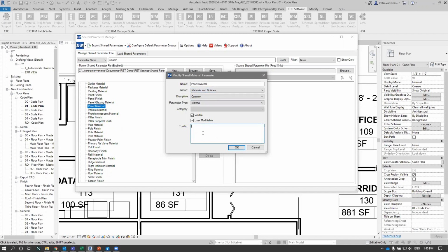I mean, we can do this stuff manually, but when we open up a shared parameter file, that text file, the first line item we see is do not change this, do not change the shared parameter file manually. It's very easy to break them. If you don't know exactly what you're doing, it's very easy to simply break an entire shared parameter file. And that can cause many, many, many problems.